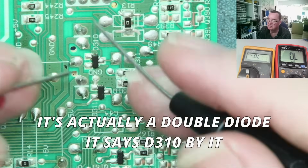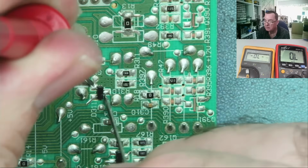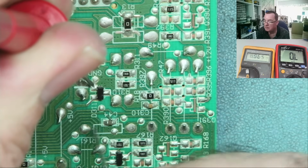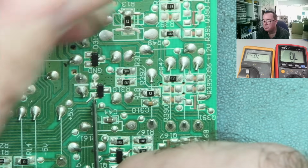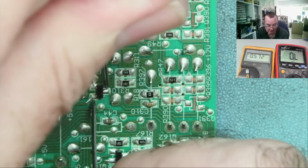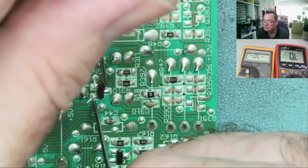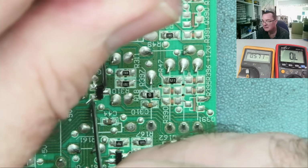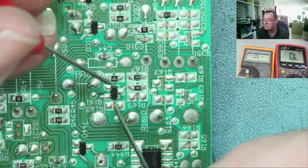So it looks like, to me, another NPN transistor, probably. This one. Like the lower value there, probably a resistor. Probably okay. I think in that direction the reading would go a bit higher, but it's not short. And there's other components around. Another one.